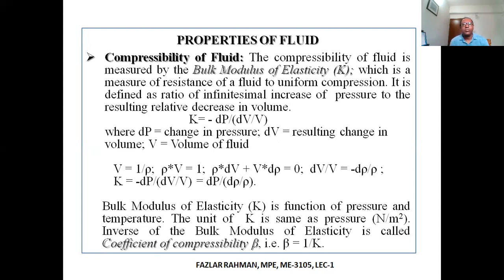So what is compressibility of the fluid? Compressibility of the fluid is measured by a constant called bulk modulus of elasticity, which is a measure of resistance of a fluid to uniform compression. That means if bulk modulus is high, it has high resistance to compression.